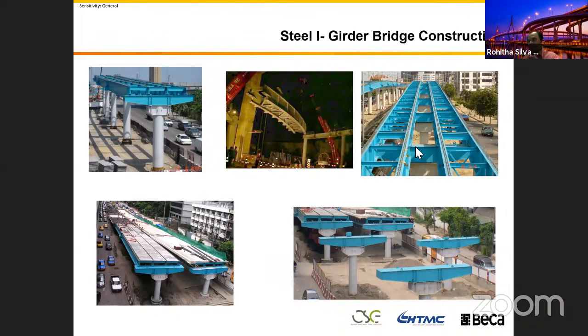In addition, the main advantage of using this form of bridge is that you can prefabricate this one in a yard. You can bring them and you can erect. Another thing, if it is steel, you can build with any form. You can say it's a curve girder bridge, the sharp curve girder bridge. I think this radius is close to 56 meters. I think we fabricate this, we lift this one on the side. So the construction efficiency is there.